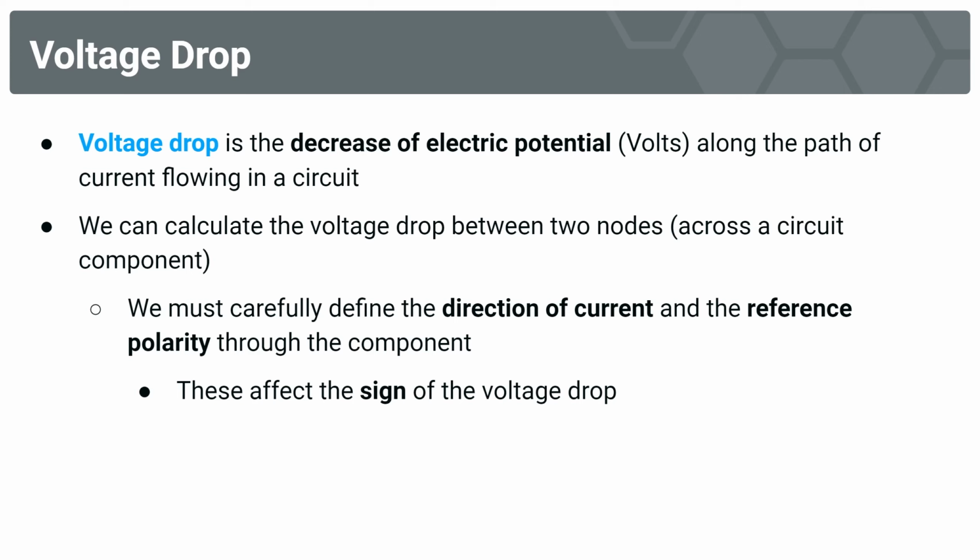Now here's an example for you. Consider the last lecture where we wanted to identify the forward voltage across an LED. Forward voltage happens to be similar enough that we could describe it also as the voltage drop from the positive to the negative terminal of an LED. And it was important in our discussion to identify the voltage drop because that determined what resistor we would need to use so that we wouldn't exceed the maximum current that could flow through the LED before that LED burnt out.